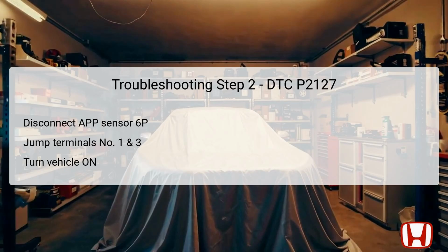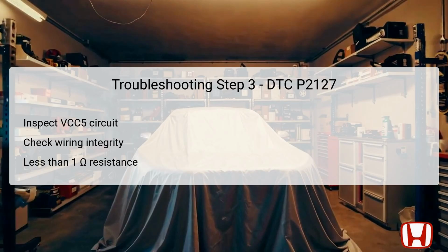This step is formative in isolating the source of the issue, highlighting the need for precise operational checks in the troubleshooting process. The next critical step involves inspecting the VCC5 circuit and ensuring the integrity of the wiring. Once more, the vehicle's electrical systems must be in proper condition, so a detailed examination should be performed with the APP sensor 6P connector and the PCM connector A both disconnected.